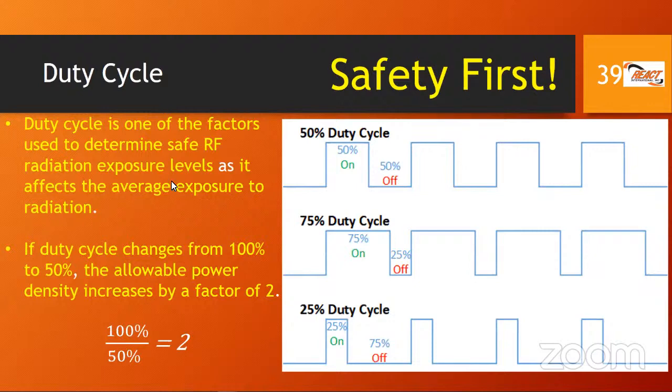The same thing applies when you're transmitting. You need to be conscious of how much you're transmitting, because the larger the duty cycle, the more exposure you have to RF, or radio frequency, and it's an important part of calculating that exposure limit. It's an exam question. Now there's an actual calculation. Initially it was a 100% duty cycle, which means it's continuously transmitting for the entire period.